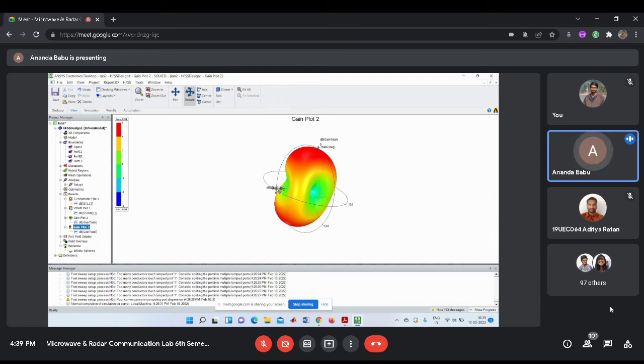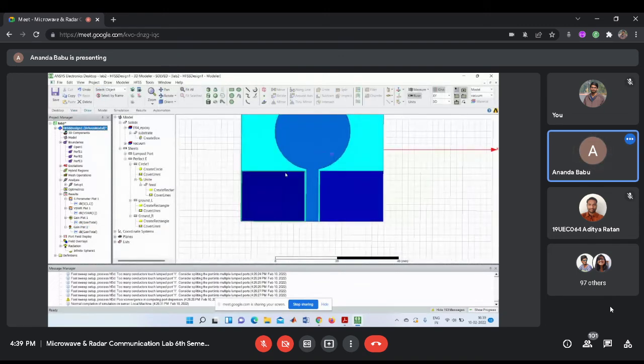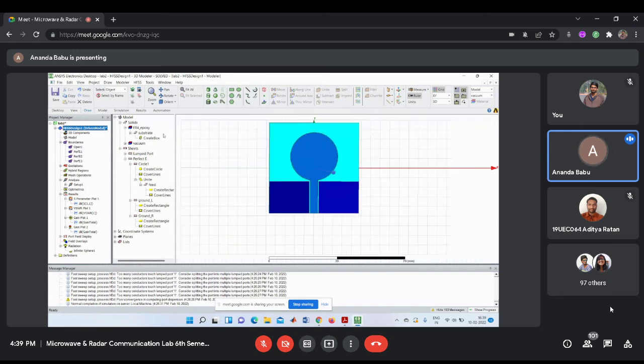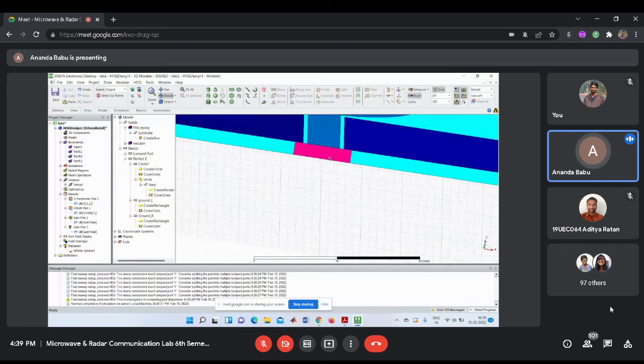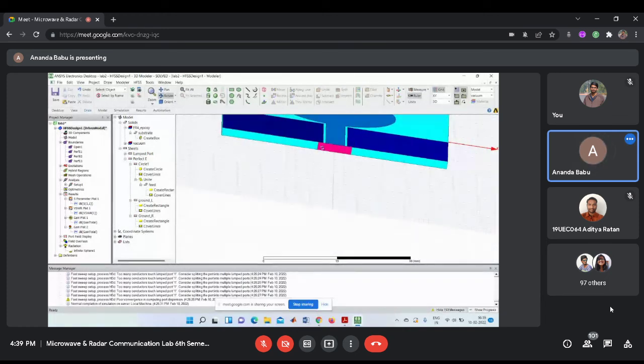So this is the coplanar waveguide feeding. Simply, coplanar waveguide means we are placing a rectangle on the left side and the right side of the main strip line. See here, the center is the main strip line, the left side is one plate, the right side is one plate. But we are giving the excitation to all. This is very important. Whatever excitation is given, it touches the left side plate, the center and the right side. So this is the coplanar waveguide.